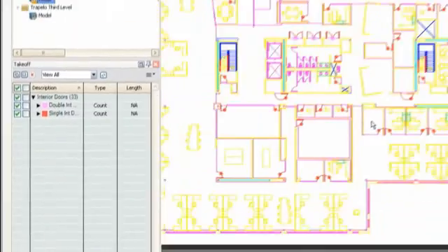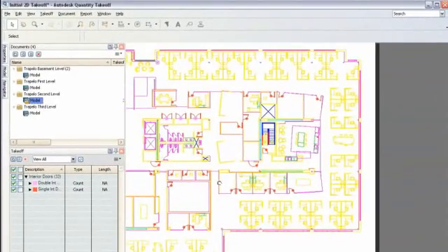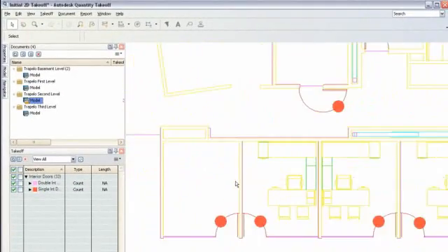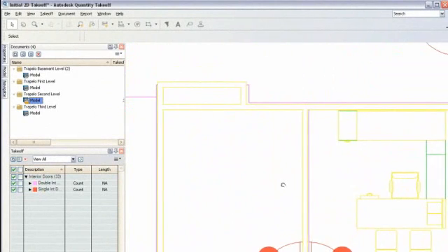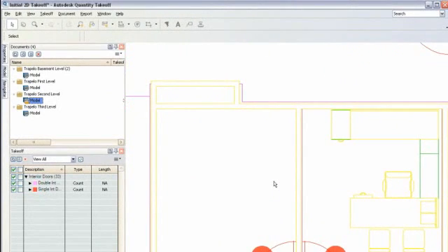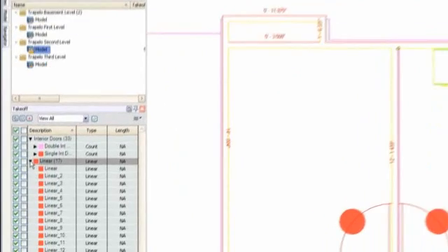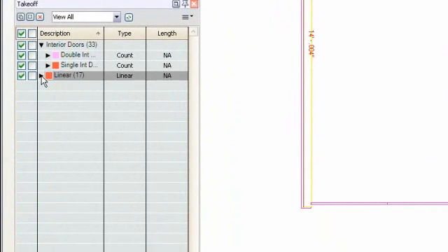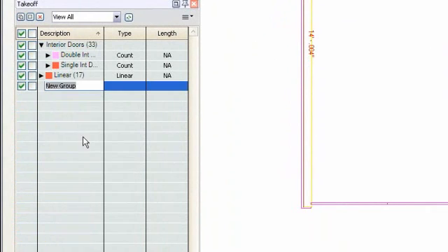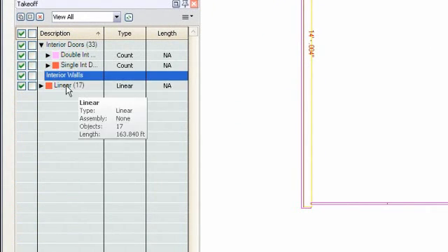When quantifying walls, for example, tools are available for you to perform linear takeoffs with a single click. Although these 2D sheets have no object intelligence, Autodesk QTO can recognize individual lines. And as we set up the scale earlier, merely clicking on a line representing a wall provides you with an accurate length. The takeoff group can be renamed to identify the object type, and if required, additional properties can be assigned, including details of the object's construction.